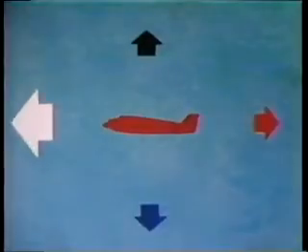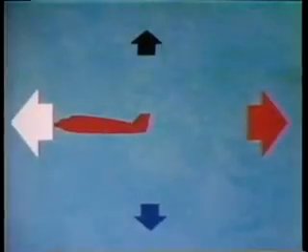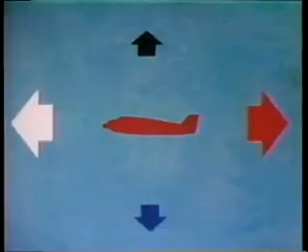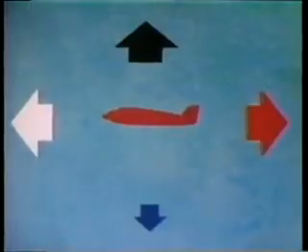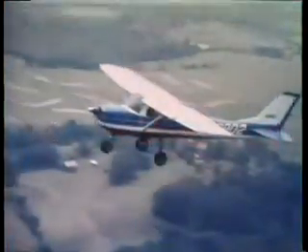But we don't just fly straight and level. We have to get up there and back down, and we want to move around. Suppose we increase power. We increase thrust. And while it is out of balance with drag, speed will increase. But drag will also increase with speed until these forces are in balance. By increasing the speed, we also increase the lift capability of the aircraft, because more air is flowing over the airfoil. The lift is maintained equal to weight by changing the angle of attack with speed.